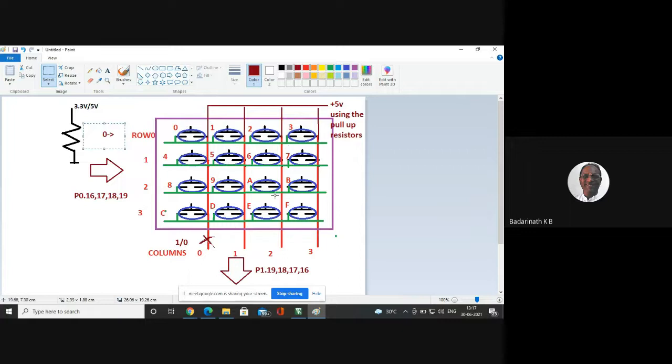Forget about the number. It's very important that the number is not important. You got the physical location of the key. Now, to convert the physical location of the key into a proper ASCII code: basically, whenever you press a key, the scanned keyboard gives you the ASCII code of the key you pressed. So you want to get an ASCII code of the key, based on the physical location. What ASCII code you should generate for the physical location depends upon the programmer's choice.